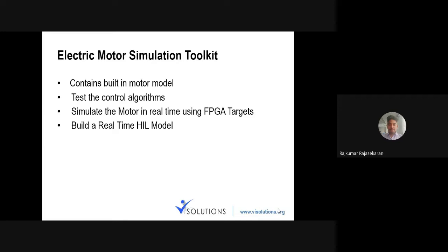And finally, it's a growing field in engineering. There is something called HIL. HIL stands for hardware in the loop, where you have two hardware units. One simulates the controller and the other simulates the plant, where the plant means the motor. Instead of having the real motor and real controller, you simulate the controller aspects in one hardware, and the motor parameters are simulated in the other hardware. The hardware which simulates the controller will be connected, through its IOs, to the hardware which simulates the motor.